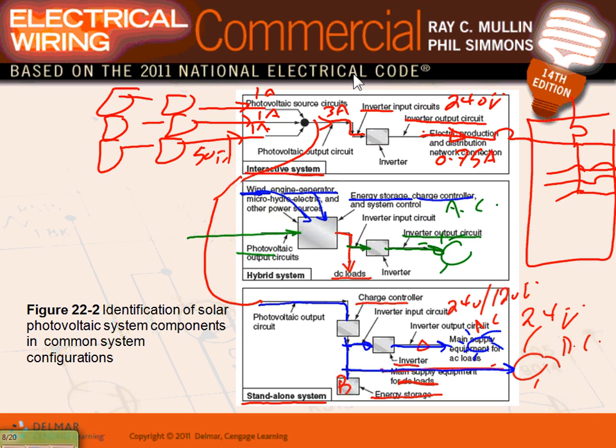Yeah, the inverters for this are very specialized because the voltage varies. There's a huge fluctuation in voltage due to the sunlight, when the sun is available, and the ambient temperature. Absolutely. So standard inverters that are made to take battery power to electricity might not cut it. Yeah, they're not going to cut the mustard because they're set.